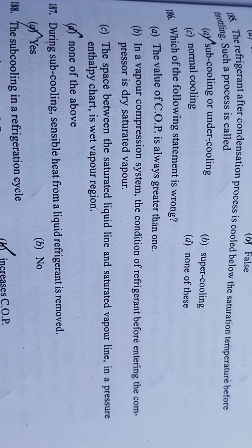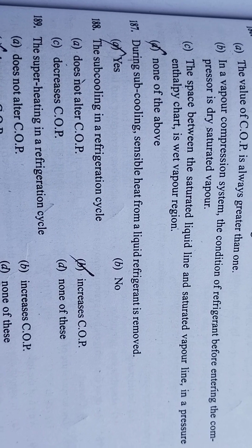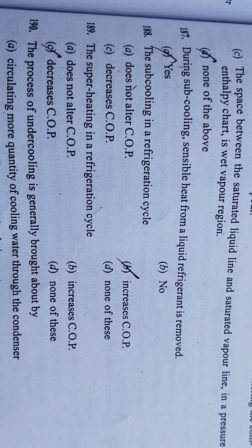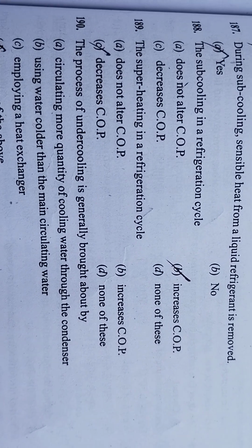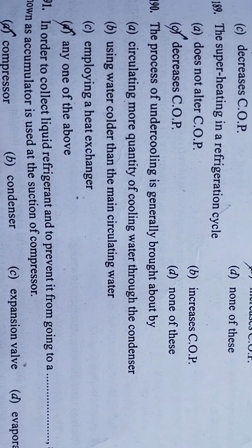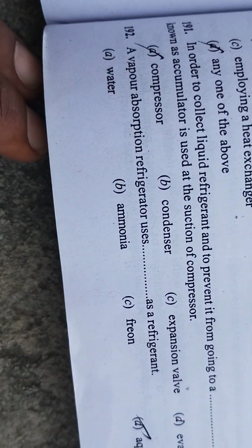Which of the following statements is wrong? None of the above. During subcooling, sensible heat from the liquid refrigerant is removed. Subcooling in a refrigeration cycle increases COP. Superheating in a refrigeration cycle decreases COP. The process of undercooling is generally brought about by any one of the above.